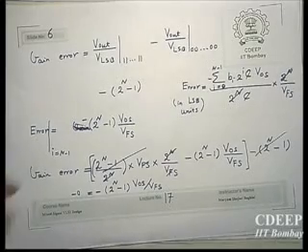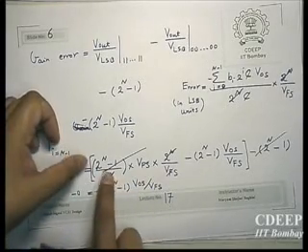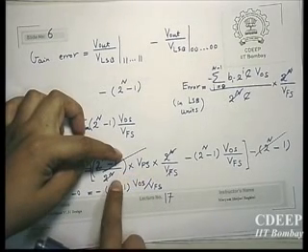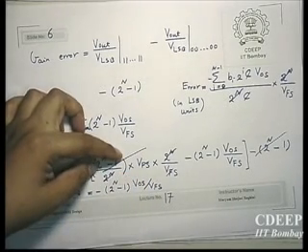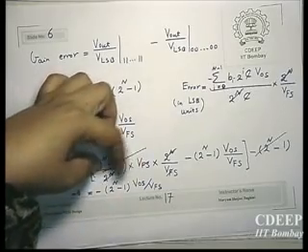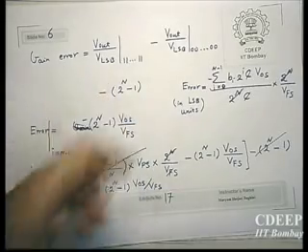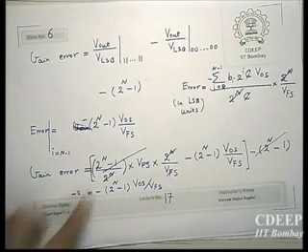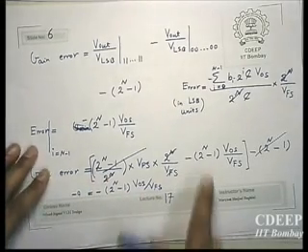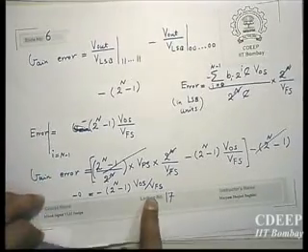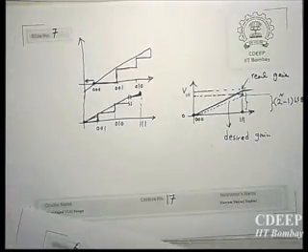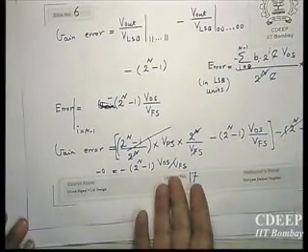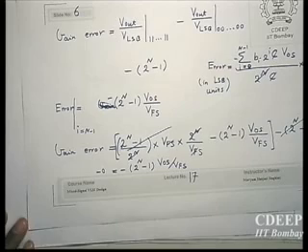Yeah, which is here also is shown like it is 2 to the power n minus 1 LSB size multiplied by V full scale upon 2 to the power n. We normalize it to V full scale to LSB, therefore it will be 2 to the power n minus 1 only. And then for this will be the deviation. So therefore deviation essentially will get that V offset upon V full scale into 2 to the power n minus 1.